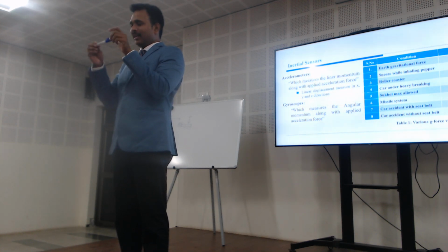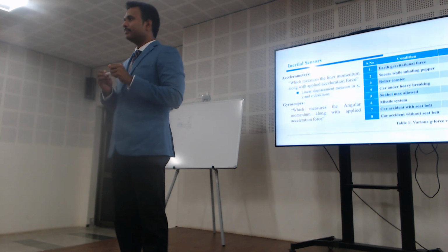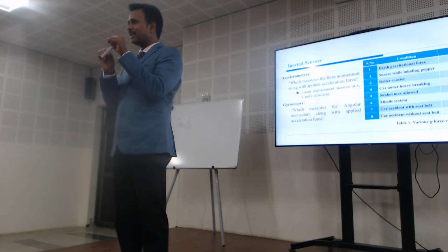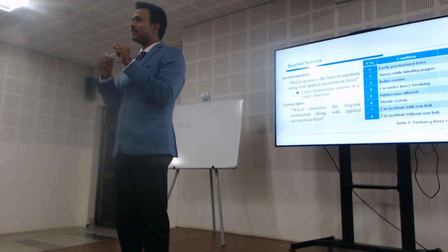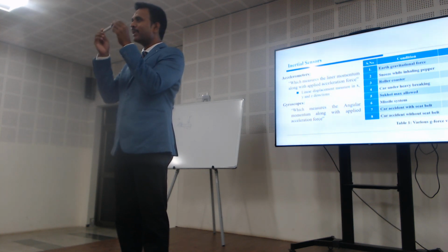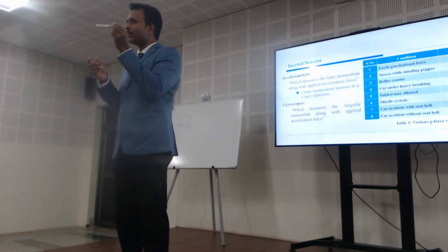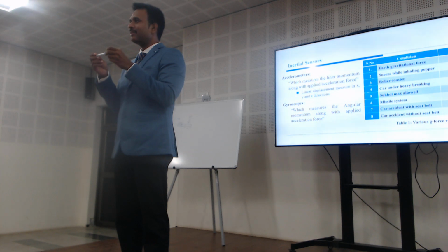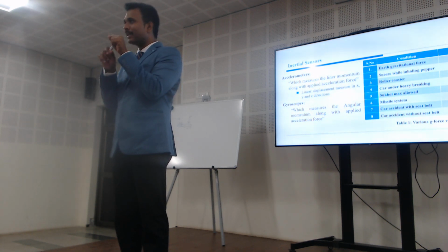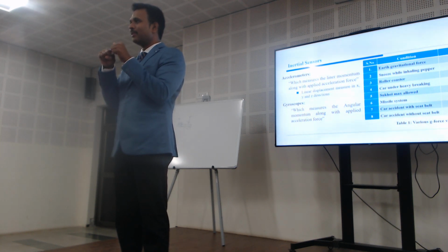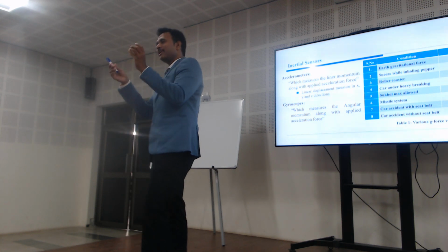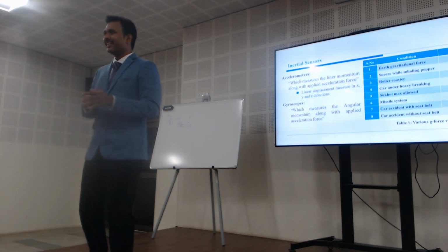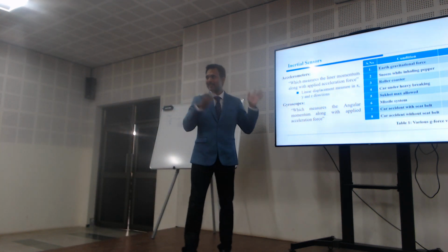Yes or no? I designed this for 30G. Whenever 30G comes, it will work. But I want to design for 1G. If I use the same structure, same width, same length, what happens? It won't bend. So that flexibility matters. That is why I said initially that only the suspension beam plays the major role in designing the sensor. Right? Here, an example means we need background.